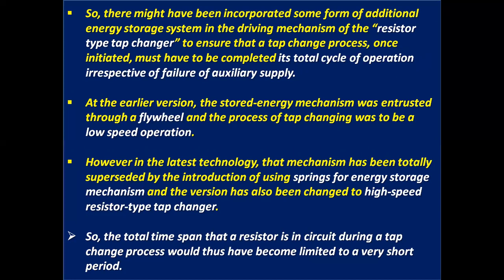In the earlier version, the stored energy mechanism was through a flywheel, and the process of tap changing was a low-speed operation. However, in the latest technology, that mechanism has been totally superseded by using springs for energy storage, and the version has also changed to the high-speed resistor type tap changer.